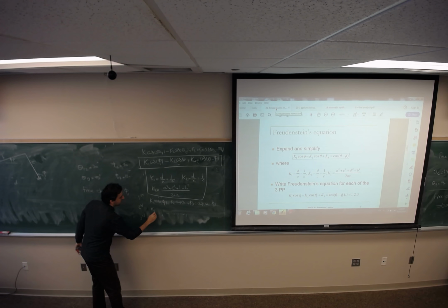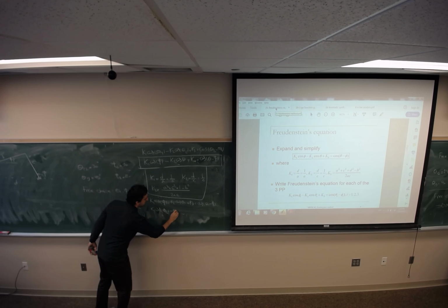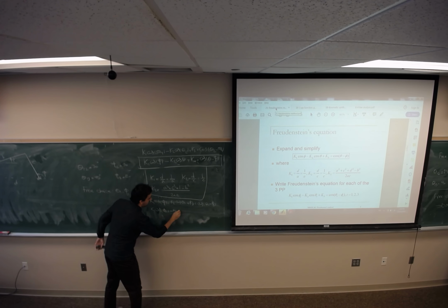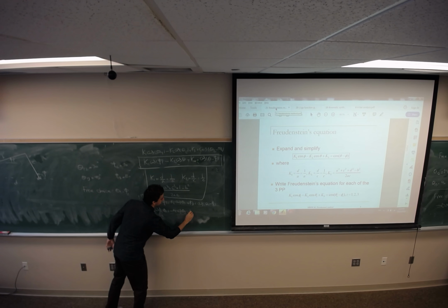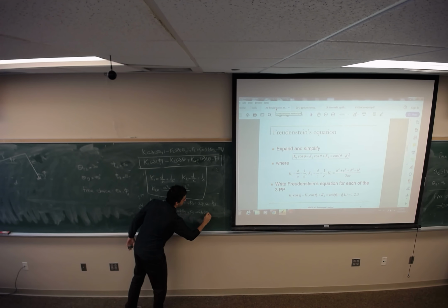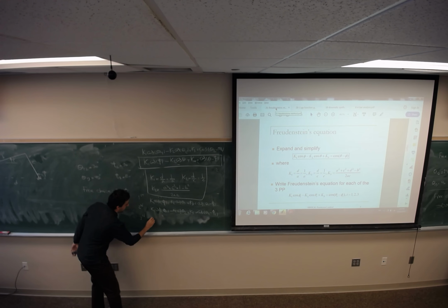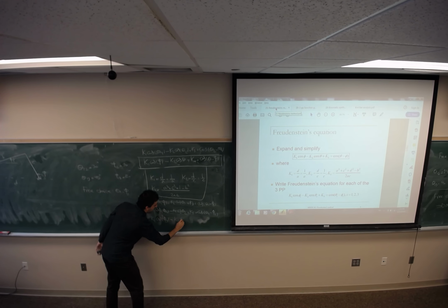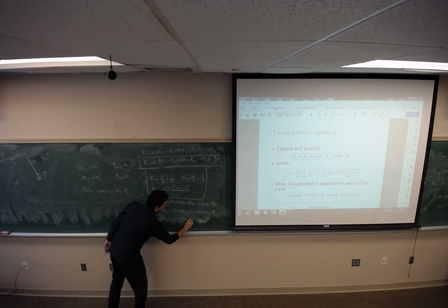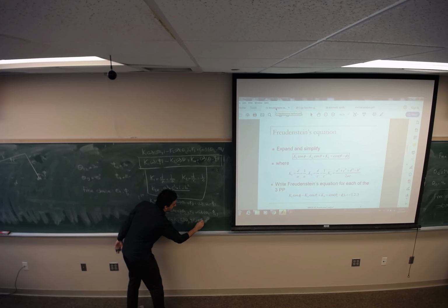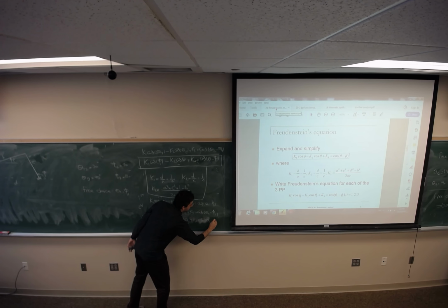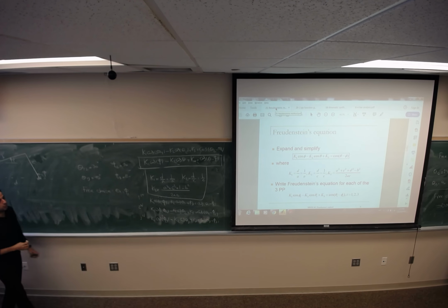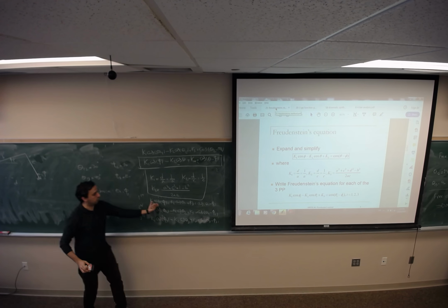Second equation, K1 cosine of phi2 minus K2 cosine of theta 2 plus K3 equals cosine of theta 2 minus phi2, and K1 cosine of phi3 minus K2 cosine of theta 3 plus K3 equals cosine of theta 3 minus phi3. You will get 3 equations which should be valid for all 3 precision points.